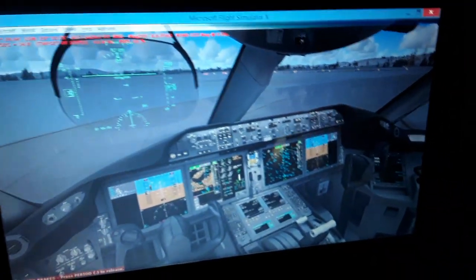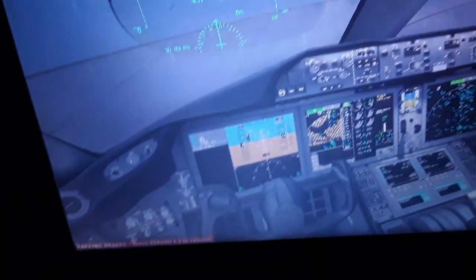You will see later. So we have the aircraft onboard antennas that receive the radio frequency from the threshold antennas of the runways, and align the aircraft with the horizontal localizer and the vertical glide slope, the angle of approach. We have also the localizer crossbars. We have the flight director crossbars for manual guidance of the aircraft, and the autopilot crossbars for automatic guidance of the aircraft. We have also the angle of attack of the aircraft as it flies in flight mode 1 and 0 with the autopilot and the autothrottle. Later on, vertical navigation modes.